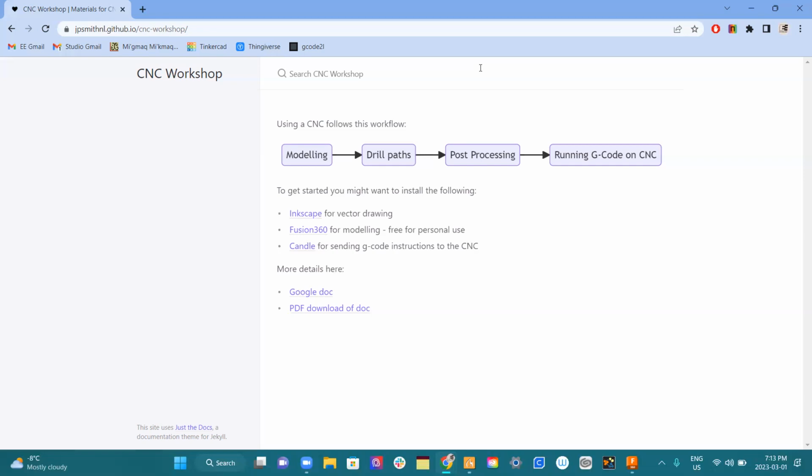When you have that whole chain of places that you need the drill to go, you export it. There's a post processor that converts the instructions to be compatible with your particular machine, because they can be slightly different. Then you have to send the instructions to the machine. It's a bit of finagling. It's not like hit print, unfortunately. I bet a really, really expensive one would probably just print, but not 99% of them.